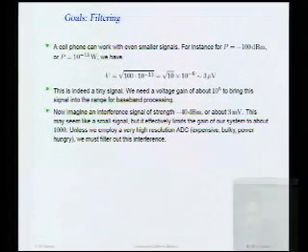Kevin? How do we know the difference between the interference signal and the signal we want? That's a good question. Sometimes we can't tell the difference. In fact, in this class, we'll talk about a lot of mechanisms which produce energy inside the bandwidth of interest, and so there's no way for us to distinguish friend from foe. Of course, if we put coding on the signal, for instance, like a CDMA kind of coding, that could gain up our own signal relative to the interferer. But in many situations where you don't have that kind of coding, you basically have to live with it.